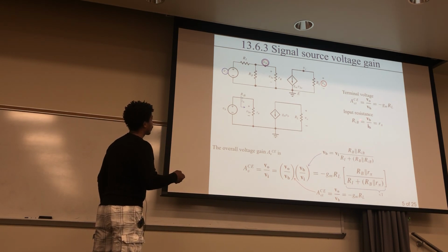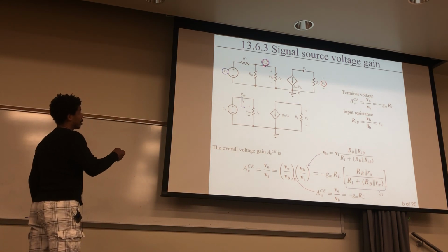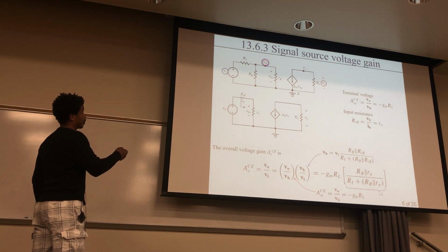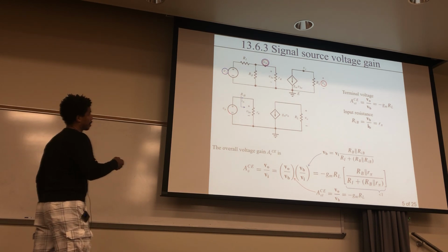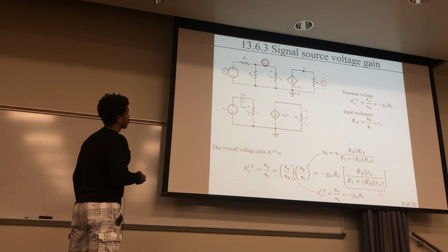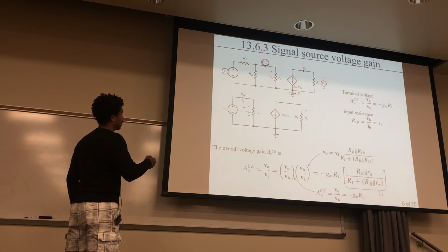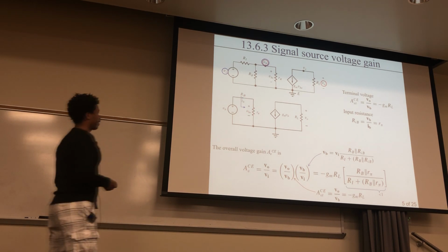And this VB right here is the voltage right here, but you could simplify it by saying, well, let's just apply that same voltage to that one. You're going to apply this voltage right here. So that's what this is. And this RIB isn't explicitly seen here, but it's the resistance seen by looking at it. So that's why this RIB just equals this R pi right there.